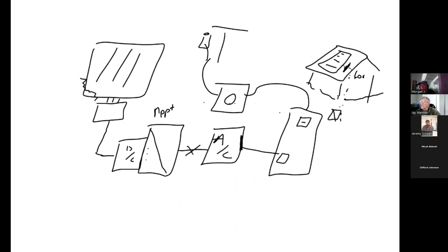So in 2014, they came out with what they refer to as rapid shutdown. And it went through a number of changes, but it basically says now, whenever you turn off that AC disconnect that's right out here, we want the power to shut off at the array. Okay. And the only way that could happen, well, if you think about it, the first solution was, okay, well, where does the power shut off? It shuts off at the inverter.